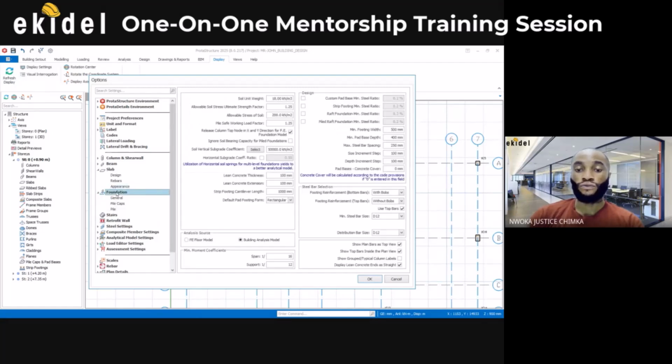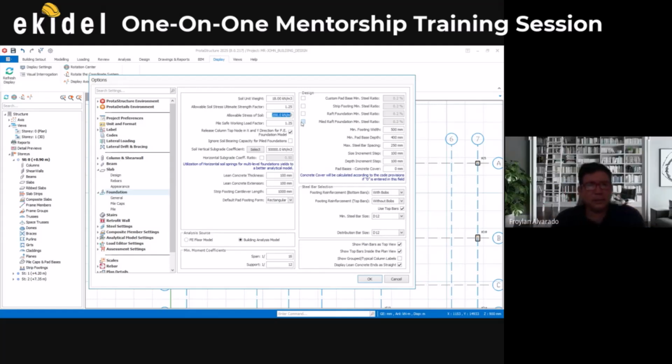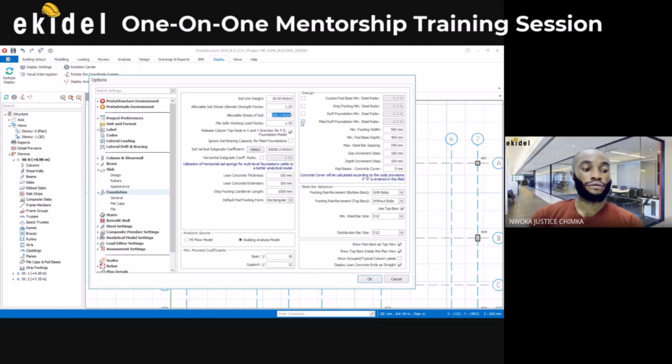On this foundation page, you'll be able to see your soil unit weights, and you have to put that in. Then, based on code, you can see your soil strength factor and allowable soil stress factor 1.25. Then here it says allowable stress of soil. That's the bearing capacity of the soil, right? Yes.